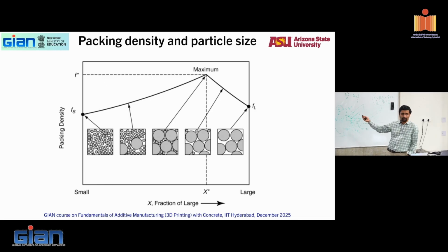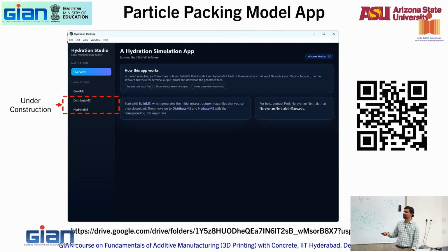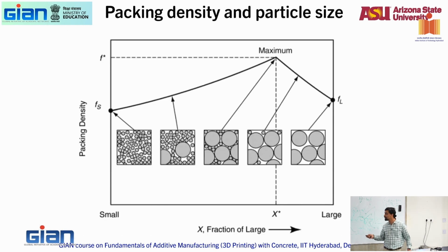All those packing density graphs you saw: there are certain particle size distributions with which you will get the maximum packing density. After that, it comes down again. I'll not talk about optimizing. I'll show you slight things with aggregates, how selecting different particle sizes gives a higher fraction than selecting very random larger particles.